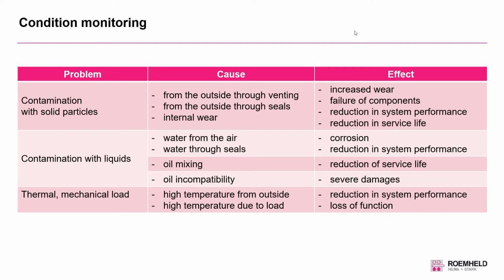A lot of components need to be vented, so this is a way that particles can get in. Also through seals, because seals have a certain amount of wear over time. So particles enter through the seal, and there is also internal wear of the entire components, like valves, cylinders, and other components.